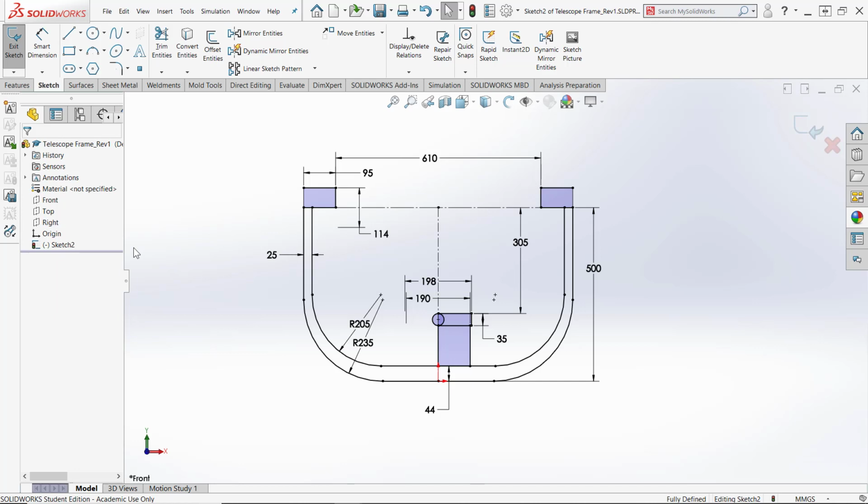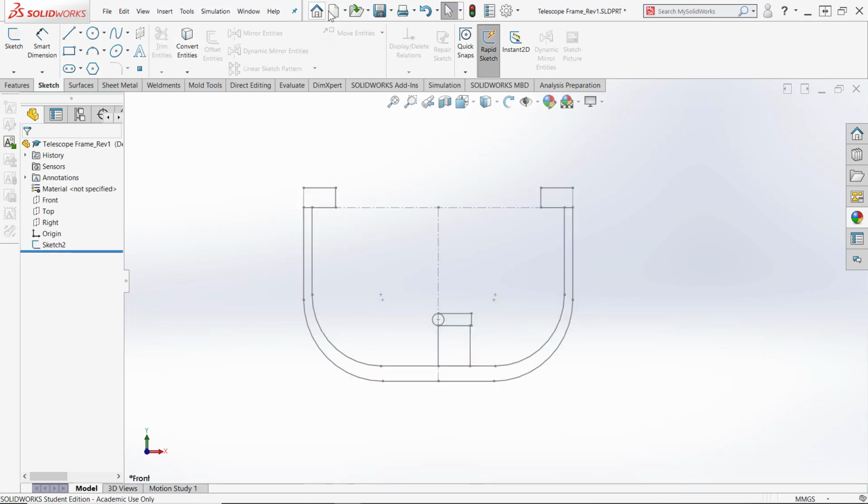Alright, I think I've got everything that I want to do in this sketch. So this is going to be the cylindrical feature in the center. There's a cylindrical boss coming out towards us and going the other direction. I'm going to revolve this about this line and revolve this about this line to give us the cylindrical features up here and up here. Alright, I'll finish sketch, and I did something right, so I'll save it.